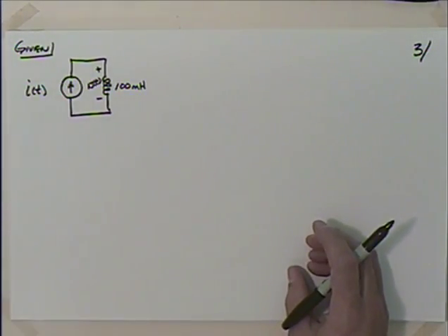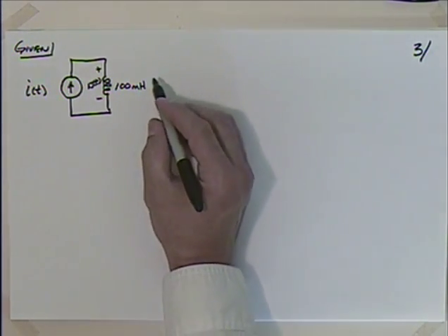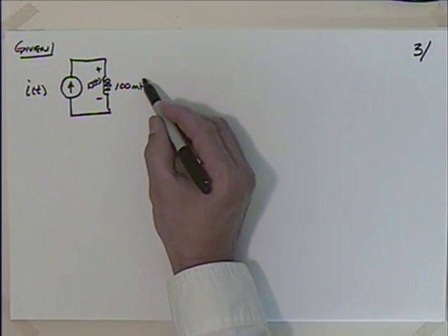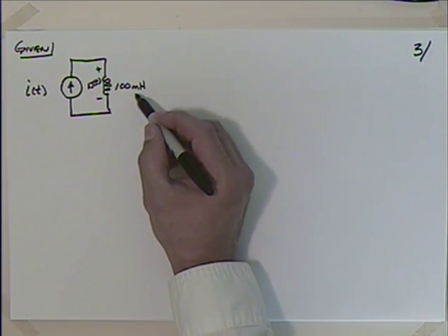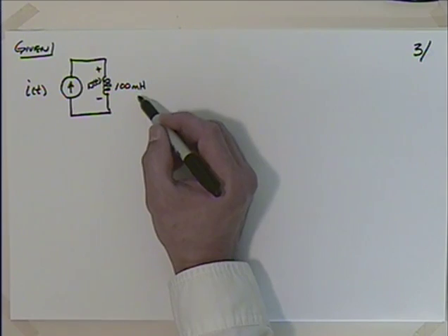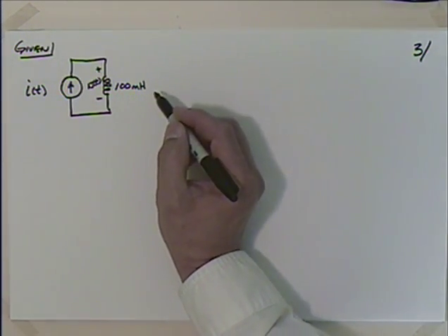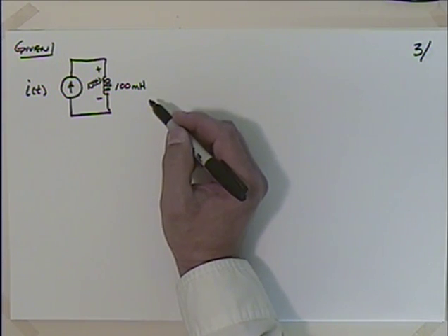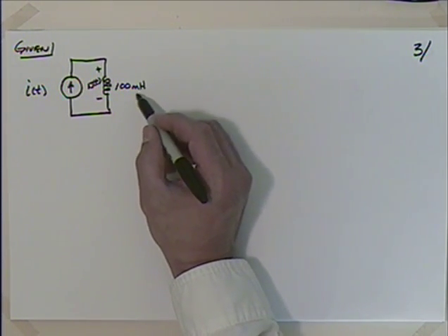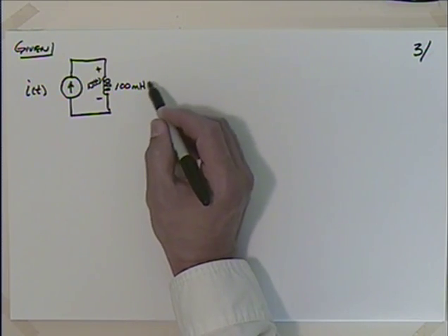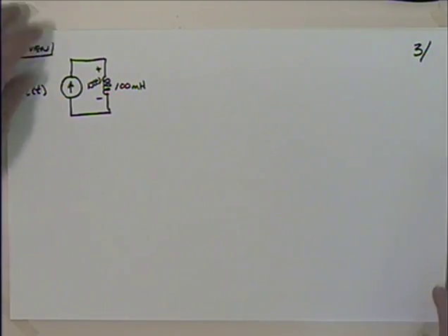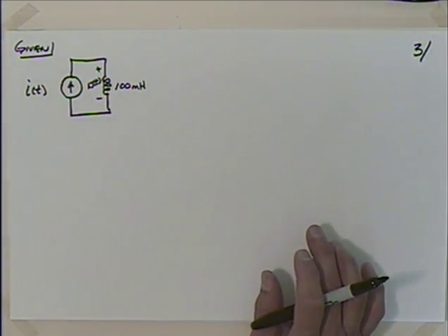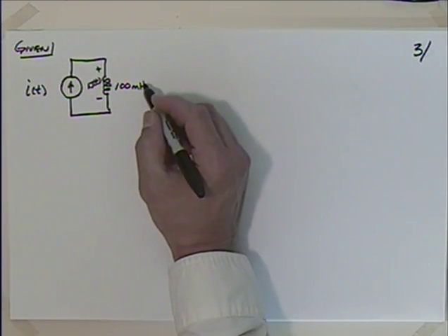And we're going to say that this is 100 millihenries, okay, which I'm not sure that I gave a very good description when we introduced the inductor. The units are henries, okay, and a henry is not as large a quantity as a farad. We do sometimes see a lot of milli or even micro henries, but it's much more common to see a 1 henry than it is a 1 farad device. So just to give you some warning there, we use a lot of millihenry inductors, but you can get up to 1, 2, maybe 10 henries, whereas a 10 farad capacitor is very, very uncommon. So this is our unit for our inductance, henries.